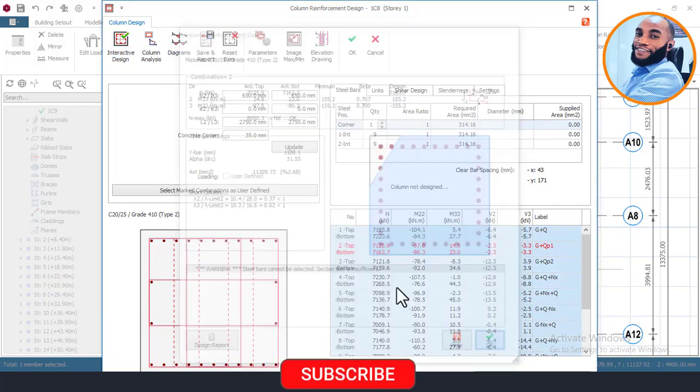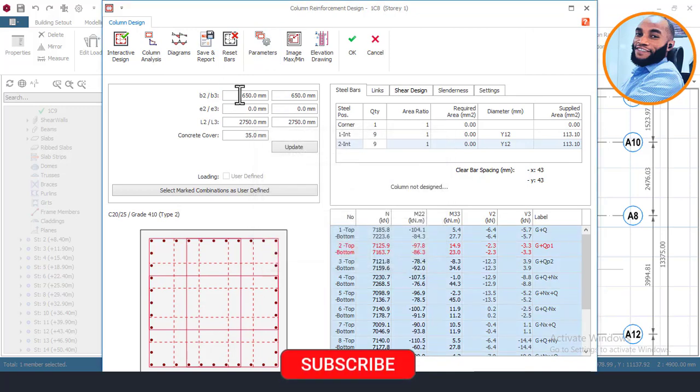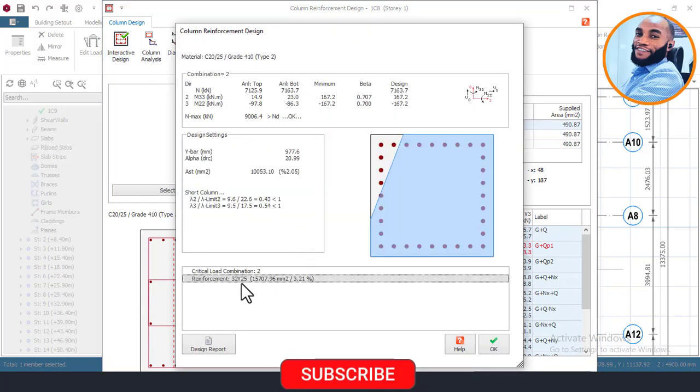Okay, that's fine. I'll now come here, click here, and then come back here, and then click back to this place. Okay, that's okay. And come here and then increase my column size to 700 by 700. And I'll come here and say update, and then reset the bars, and come here and check design again and see. Okay, right now it is okay.